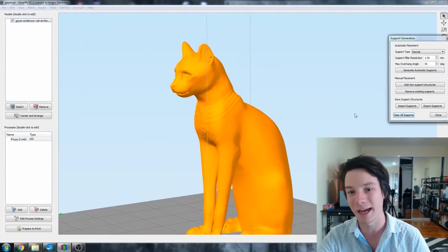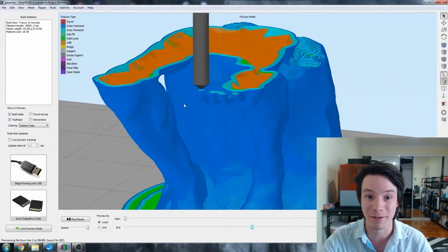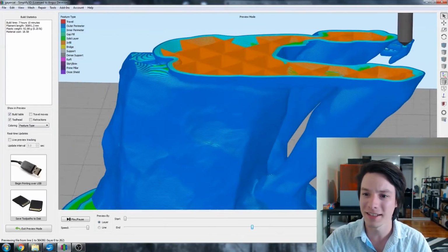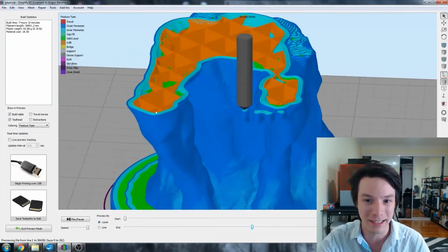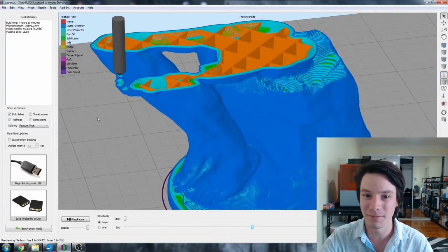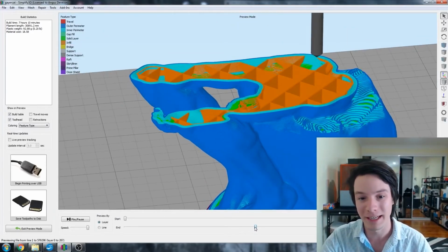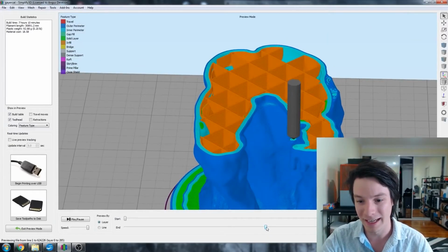But other times we have a model with lots of intricate detail and we have some overhangs where we don't really want to have that scaffolding or that support system in there. It's hard to get to, it's going to look messy, and it's going to leave something in our design that isn't actually there and shouldn't be in our prototype. Now, there's no real workaround for this because the 3D printer must have its supports in order to be able to function properly without failure.